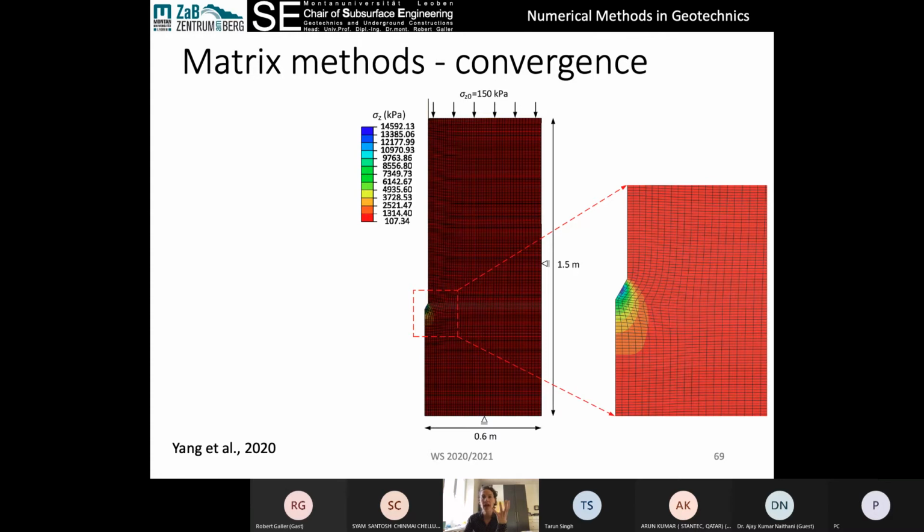A finite element code can't actually demonstrate failure because it's a small strain code, so it can't actually cause squeezing or full-on failure like a discontinuum code can. What it will say is, I can't converge because the accelerations are too much, things are continuing to accelerate according to perhaps gravity or whatever it is. And that's an indication that your excavation might fail, and you have to come up with some other design solution to prevent that failure of the excavation. So even though an error might be frustrating, it also is giving you information about your system.